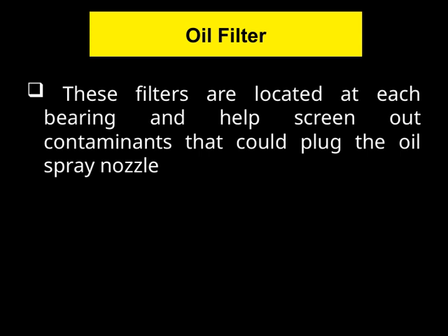It's really important to understand that these filters play a crucial role in maintaining the health of the entire lubrication system. By catching dirt, debris, or any other unwanted particles, they prevent clogs and ensure that the oil spray remains unobstructed. This way, the oil can reach the bearings effectively, providing proper lubrication and avoiding potential failures. So, always remember that these filters are a small but vital line of defense in keeping the machinery running smoothly and efficiently. Let's take a closer look at the anti-drain check valve.